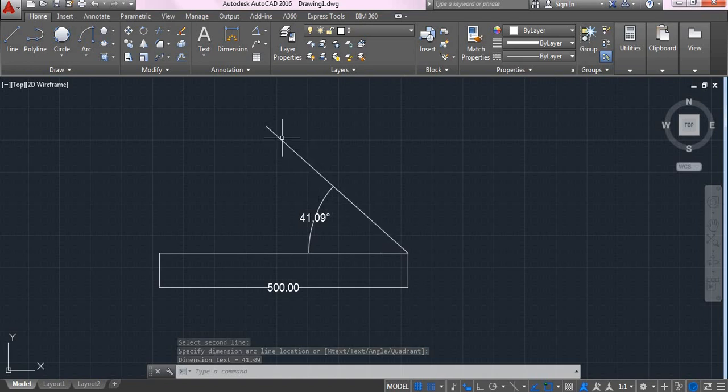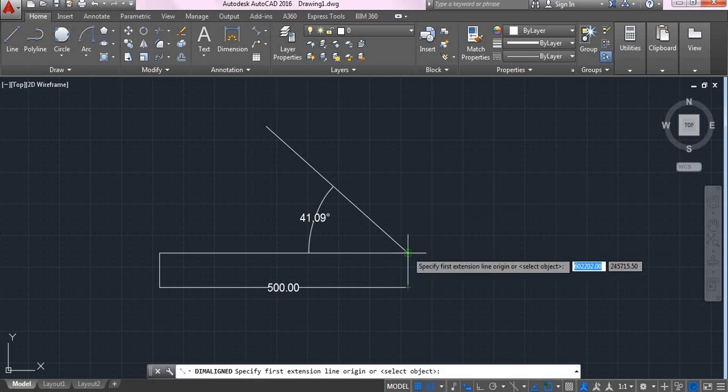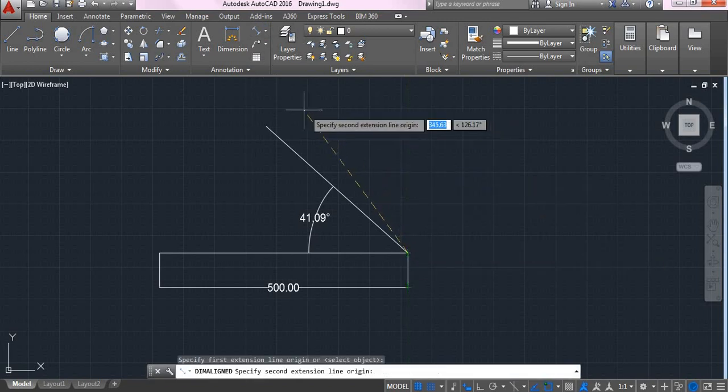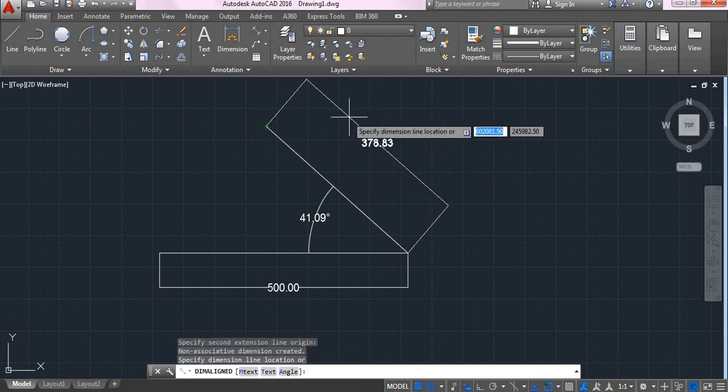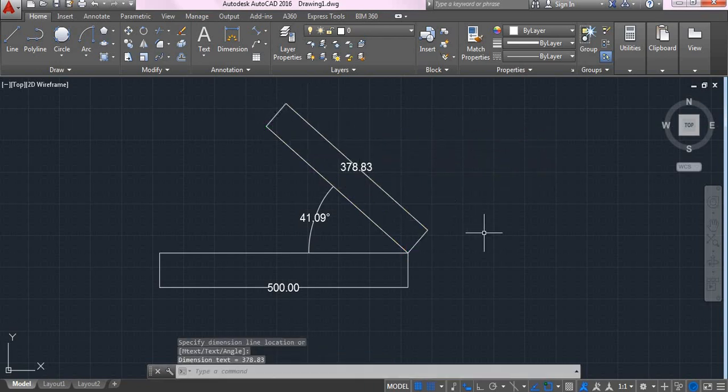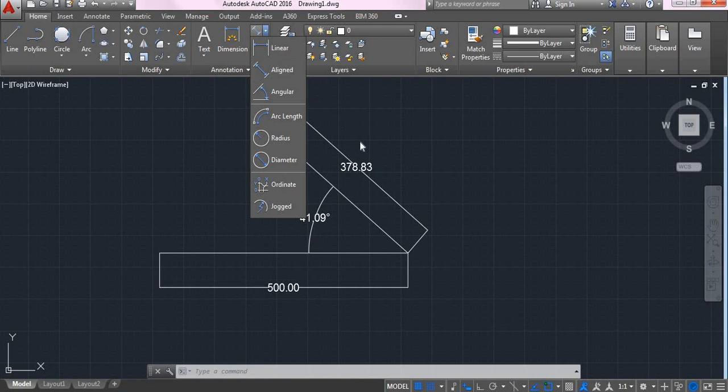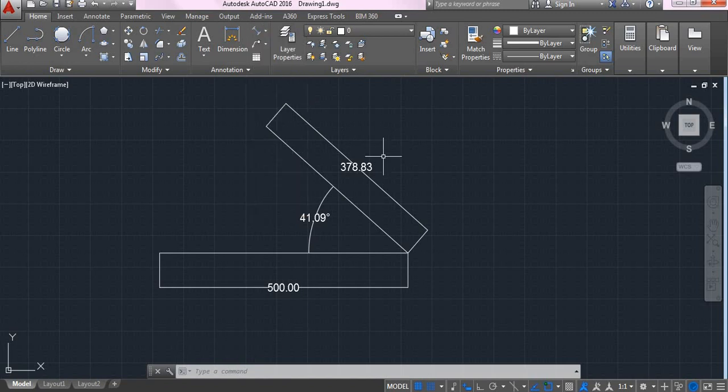And also, in order to give aligned dimension, for example, if I want to give dimensions to this aligned line, so I go for aligned dimensions and will specify the line. This line, I mean end of a line, and this end of a line, so that you can see aligned dimensions like this. So this is how aligned dimension is used. Then next we have radius, diameter and then arc length.